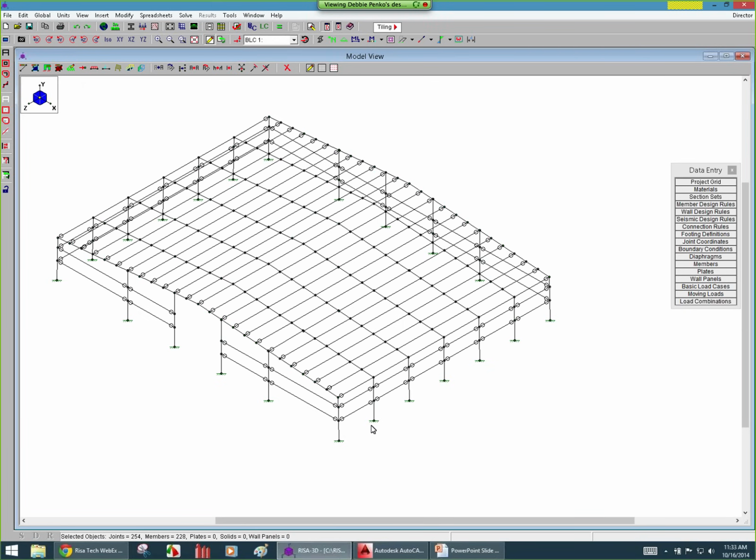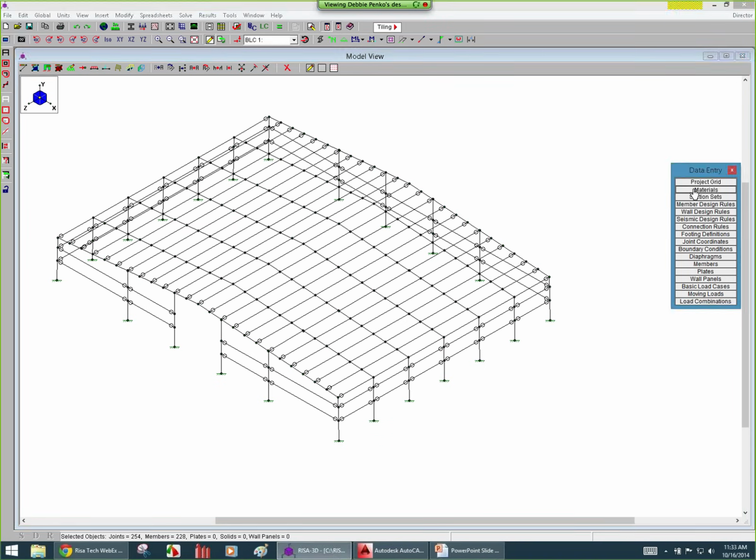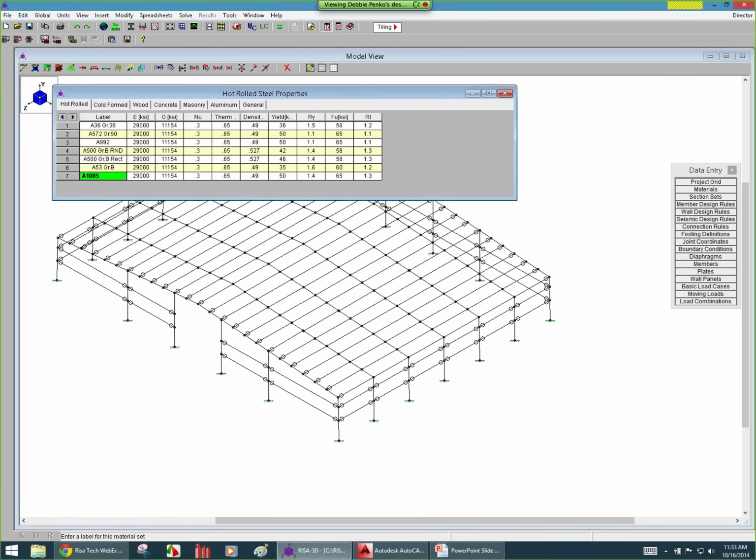We can draw in just a cable member or a solid round, but it's really important to add a material type called cable, or whatever you'd like to call it. When we add this cable element, we're going to drop its density down to 0. Why that's important is that if you were applying self-weight, you'd get loads on that cable element and deflections that wouldn't be realistic as you start to apply the loads there. They'll start to become a problem, and they won't behave like cable elements unless they have a 0 density. So we'll start with a cable element with a 0 density, and then we will start drawing.